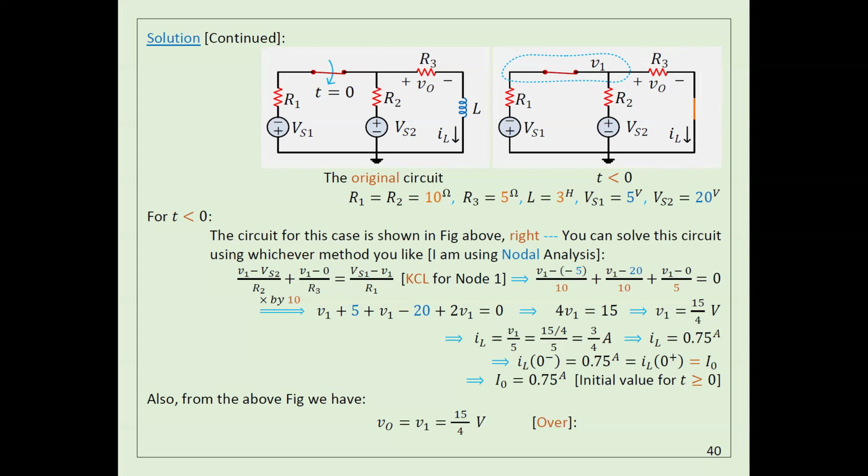So that means before we open the switch, this was the current. This is my initial current. Remember, in the case of a capacitor, you need to calculate the initial voltage. This topic is exactly similar to what I explained before, but there are some differences, and you need to consider these differences. In the equation with the capacitor, I need to calculate the initial voltage. In the equation with the inductor, I need to calculate the initial current. So this is the initial current here.